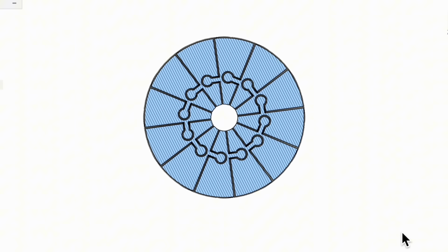Before we start sketching, let's take a quick look at the design logic of this fidget ball. The whole thing is built from several identical segments, arranged around a central axis to form a complete sphere. At the center, there's a small clearance hole. This prevents the inner tips from fusing together during 3D printing and also helps reduce friction between the segments. Each segment has a raised rail on one side and a matching groove on the other. The neighboring segments interlock with each other, linking together like chain links around the sphere.